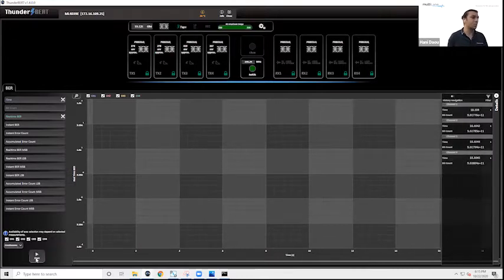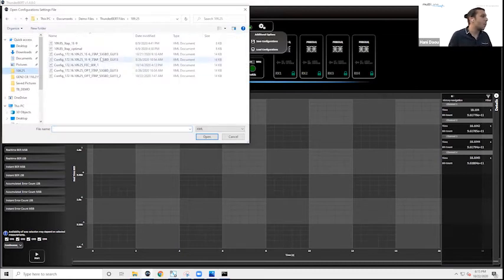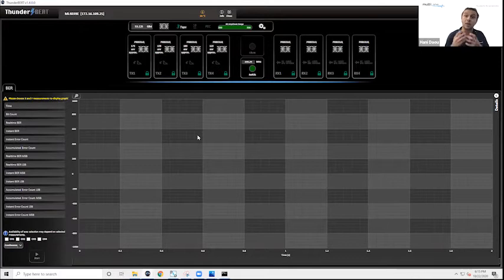But the thing is, we're not in the business of optimizing alone. We need to figure out how we can enable you guys to say, yes, my DUT works with the cleanest signal, but does my DUT work with a less power hungry signal that is more realistic of the production environment? Now, what I'm going to do is load a configuration where I have my transmitters in a more efficient mode, which will naturally result in a high bit error rate.